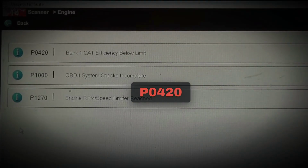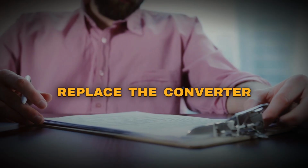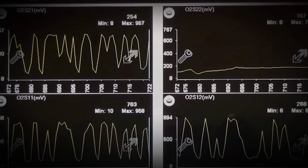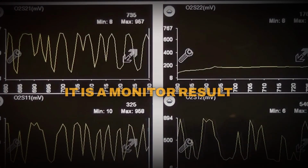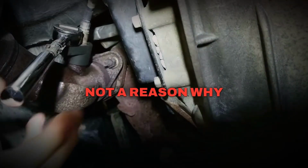Your scanner shows P0420, and the estimate says catalytic converter. The car may still drive normally, and the converter may truly be worn out. But P0420 is the result of a catalyst efficiency monitor. It is not a report explaining why that monitor failed.